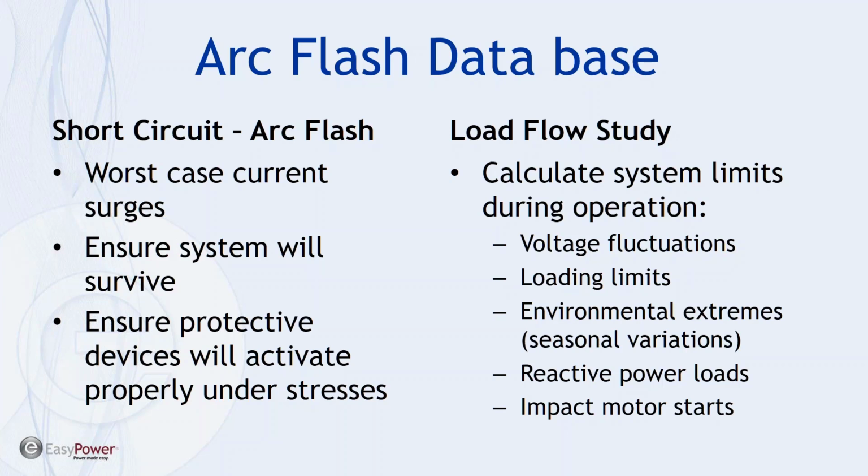Now, if we look at what it takes to do a load flow study, the difference is we're looking at normal operations. And that includes the ability to anticipate or predict voltage fluctuations due to loading changes, aging changes, maintenance issues, and likewise environmental variations.